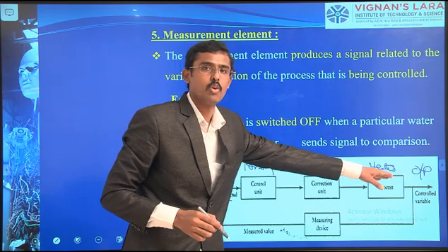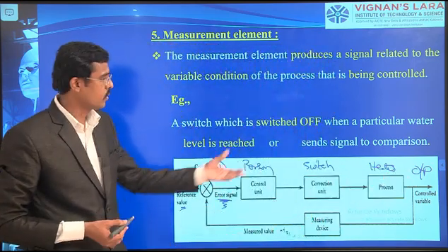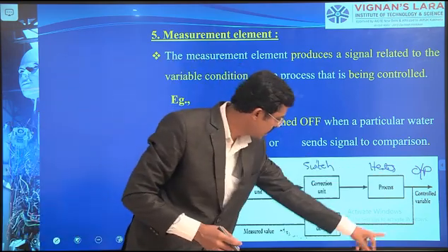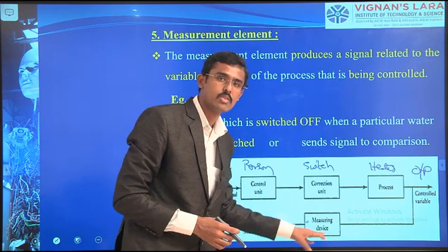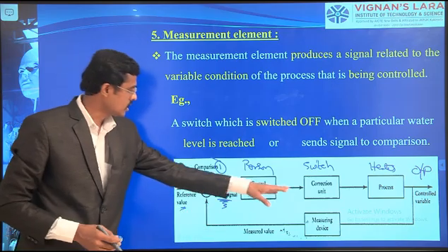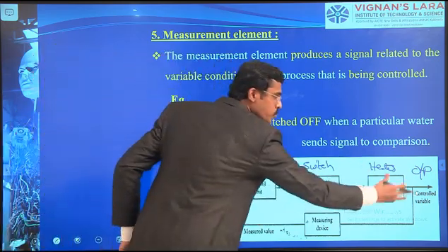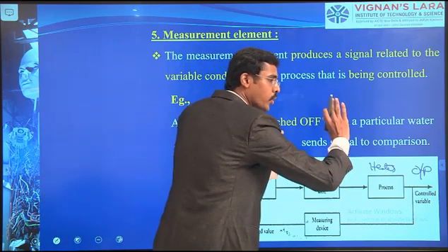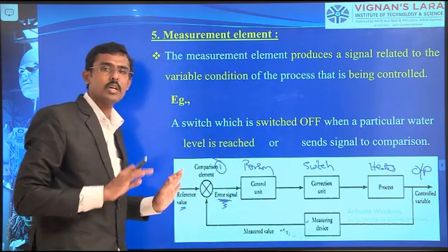And then we are measuring output, with a thermometer or tachogenerator, speed measurers, whatever it is. Right? Level measurers. Okay. So there we measure, and here the measuring device may be a thermometer, maybe a tachogenerator, right? Or speed measurement. Such things are again connected to the error signal. It is a closed loop cycle. If these three have an open loop, if we add the additional two, it will become a closed loop.